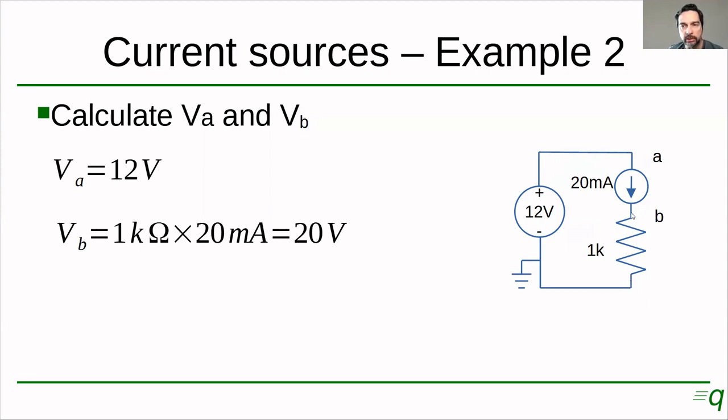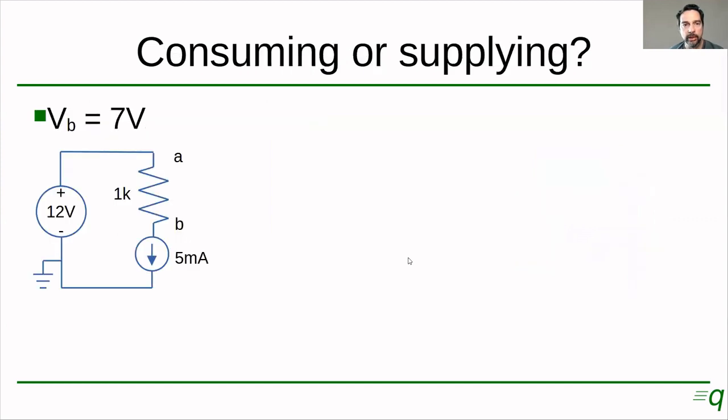So the voltage at point B is going to be the 0 that we have here because it's ground, plus the 20 volts. And again, this may be catching your attention because the voltage at some point in the circuit is higher than the voltage from our voltage source. Okay, and we're going to see that in a minute, like I said.